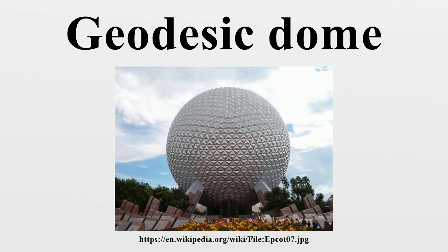The panelized technique allows the builder to attach the plywood skin to the triangles while safely working on the ground or in a comfortable shop, out of the weather. This method does not require expensive steel hubs. Temporary greenhouse domes have been constructed by stapling plastic sheeting onto a dome constructed from 1-inch square beams. The result is warm, movable by hand in sizes less than 20 feet, and cheap. It should be staked to the ground to prevent it being moved by wind.